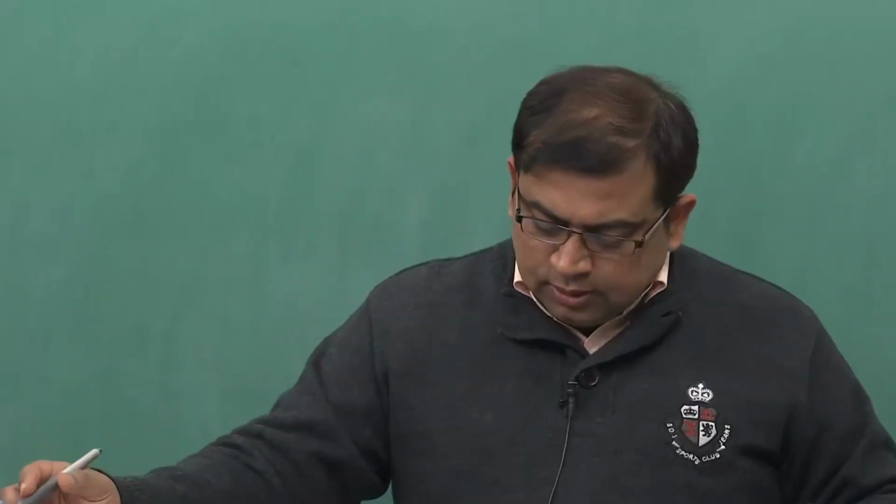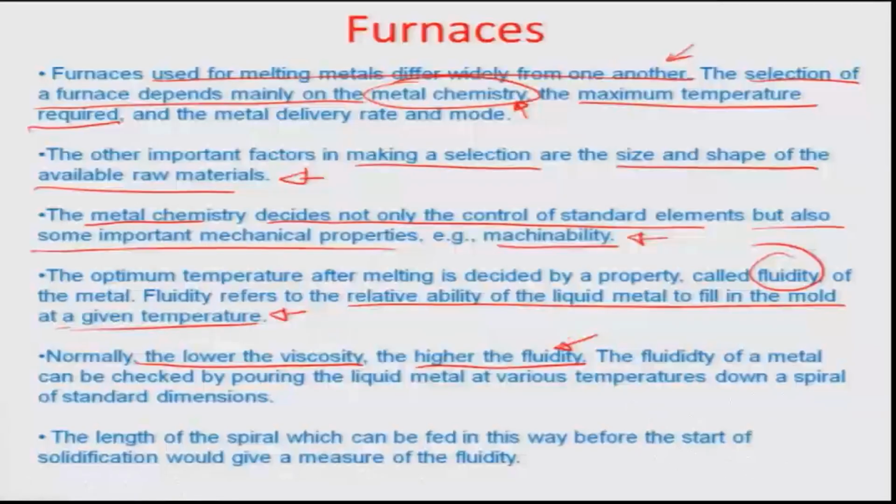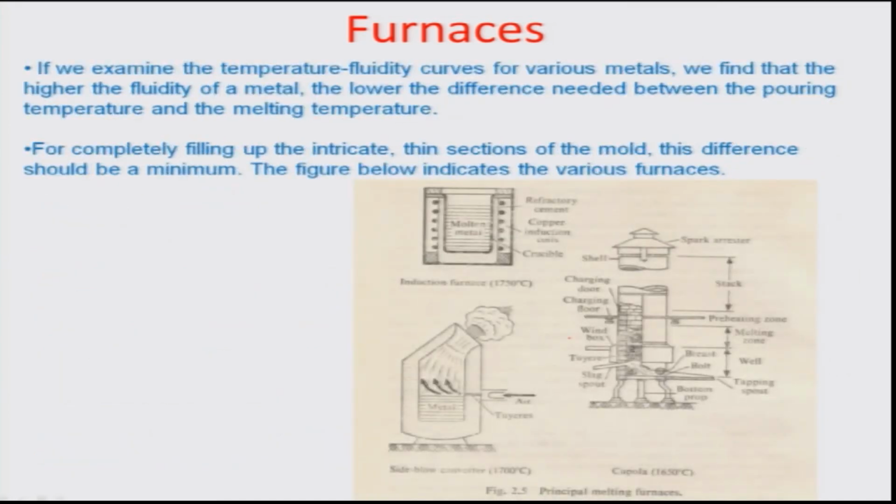The fluidity is always checked before doing a casting or pouring into a mold, so that you can see whether the output material that you are getting out of the furnace is of the correct fluidity, or the correct level of requirements imposed by the molds.